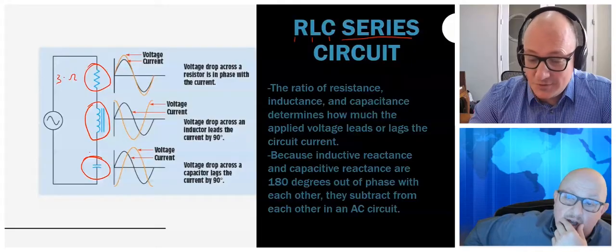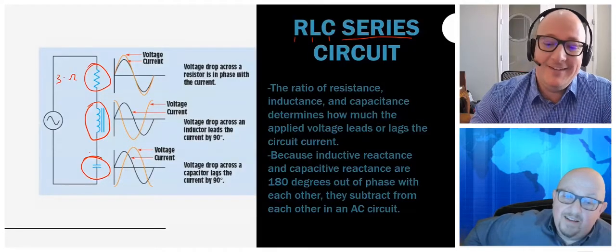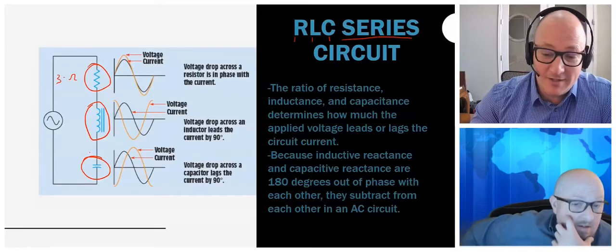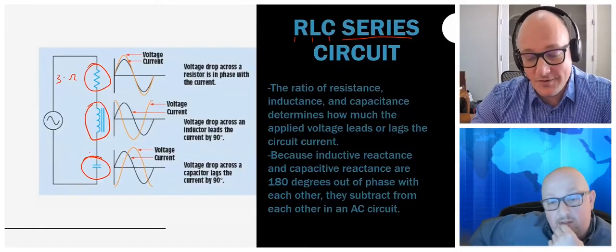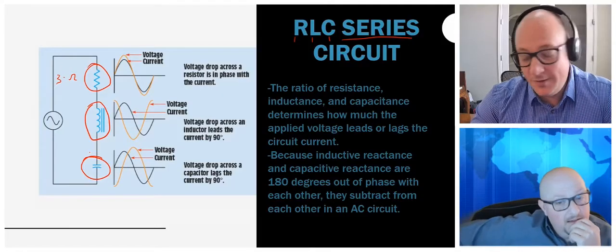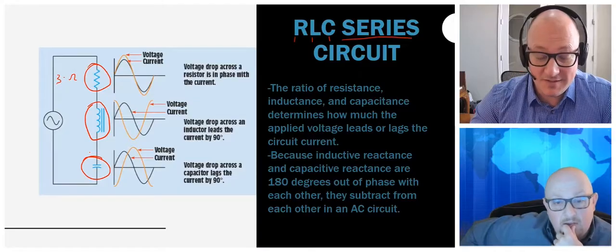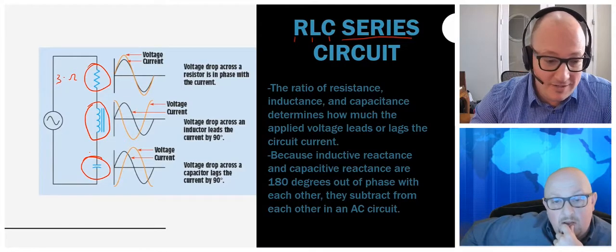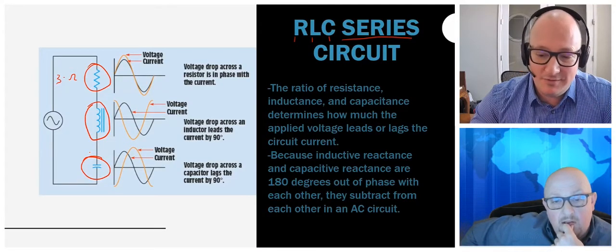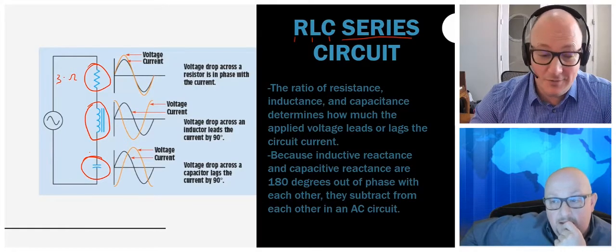That still holds true as well, but you got to bring in the Pythagorean theorem, right? That no longer is the resistance or the total opposition, whether it be an impedance, because we've got reactance and resistance now. They just add together in series, but they need to be added vectorially. They're going different directions.